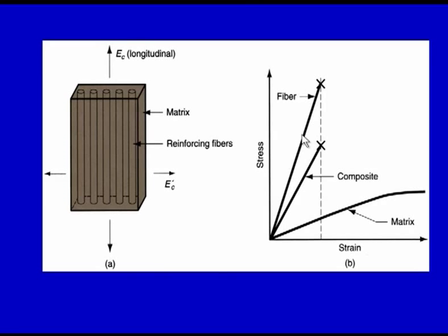So this particular diagram represents physically how the reinforcing fibers are used to reinforce the polymer matrix, and then we have properties which are different in x, y and z direction. And here with the stress strain curve we can very easily see that the composite represents both the macro constituents. The constituents are the fiber and the matrix.